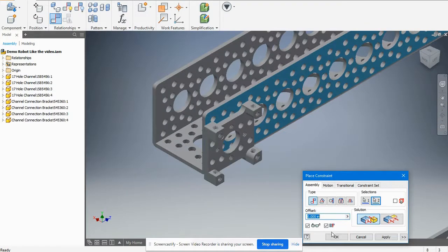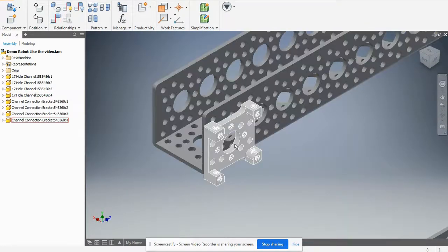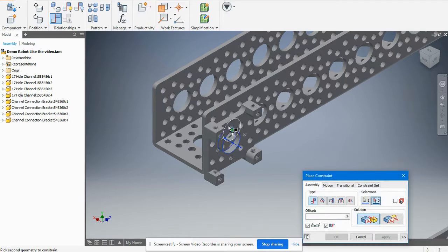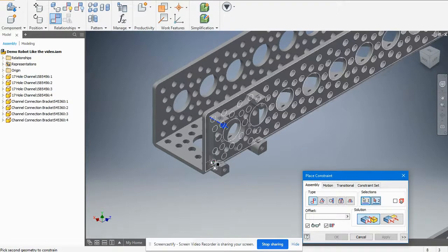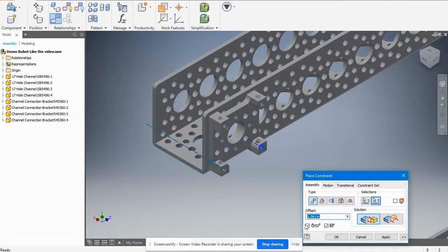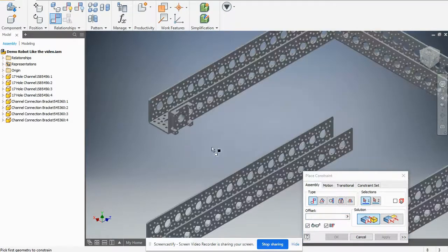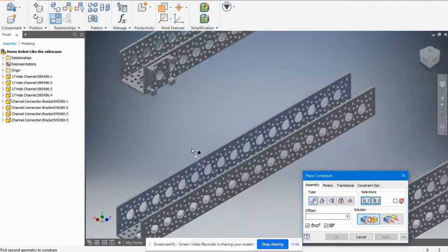to the bracket. So we're going to click on the bottom of the bracket and the side of that channel again. Didn't get it in the middle, so we're going to move that up to the middle, hit 0, just type 0 into the box, click on there, and then rotate it 90 degrees by going to the corner 90 degrees of it, press 0, and that'll work.